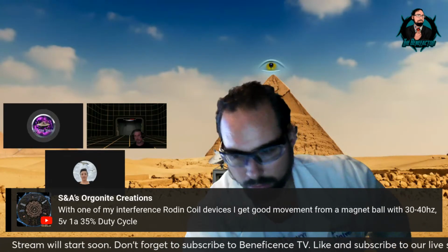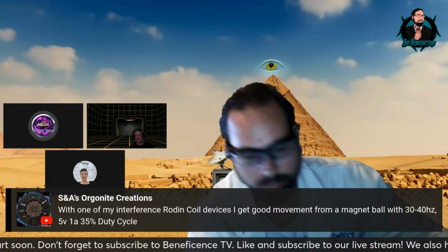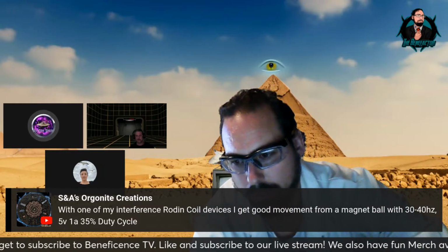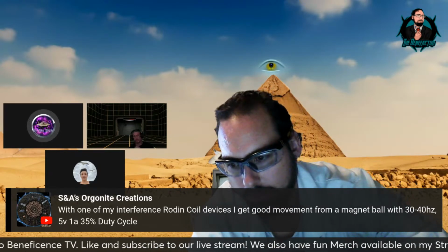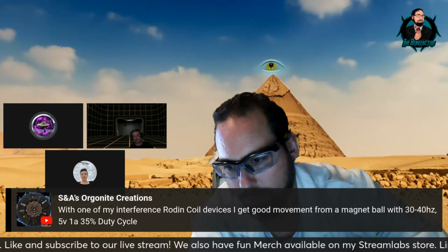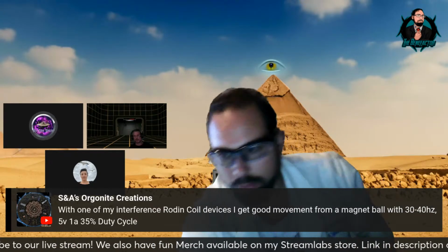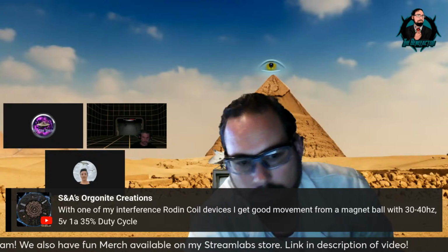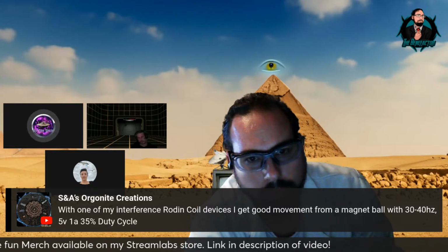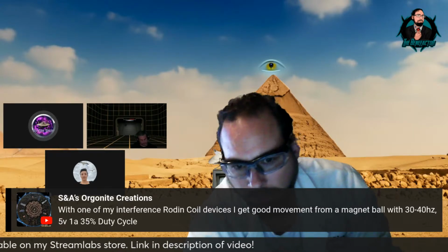So one thing I will tell you is when you got that magnet with the DC, if it jumps and then does nothing, that means that you don't have either the frequency right or the frequency range right or the pulse right, because it feels like it's on all the time. So it'll jump once and then do nothing. Well, he had it at 7.43 hertz with the AC signal, and it was operating like that. That's a low frequency.